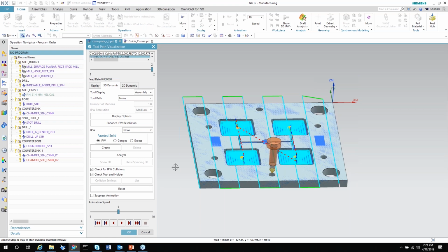So what we've done is we loaded their machine tools up with 30 tools. All of the drills and taps and common end mills and insert drills are loaded and they always maintain the same tool. So what we've done is we've changed these conditions so that no matter what feature it finds, it will use current tooling to make the feature instead of loading dedicated tooling for a feature.